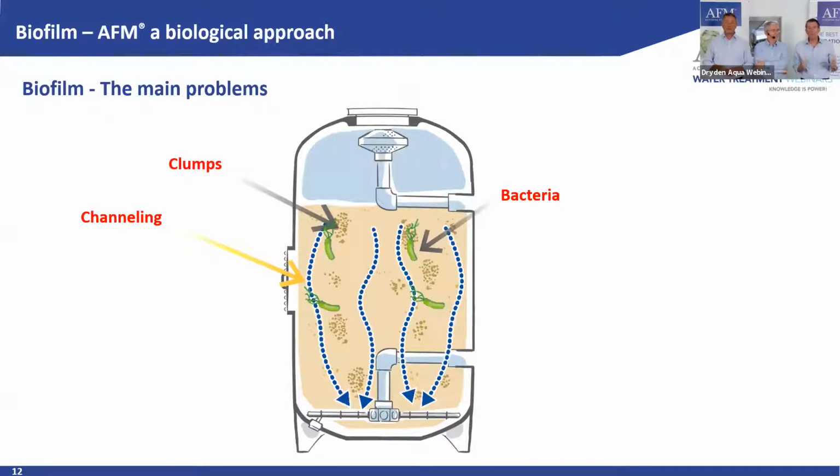This happens, for example, in a wastewater treatment application much sooner than in clean water filtration, but it can happen anywhere between 2 months and 6 months, maybe 12 months in drinking water. The more the load, the more the temperature, the poorer the backwash regime, the more you have this. And if it's channeled, you bypass your filter media. Exactly, you have highways, you bypass it.